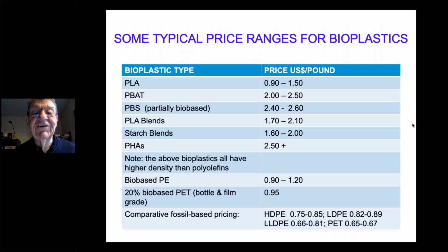So let's talk about markets now. The Achilles heel of all of these bio-based and biodegradable products is price. You can see here, these are ballpark figures, but they give you a good idea that these are very expensive compared to standard petrochemical products, which are down here on the right. The cheapest is just the lowest grade of PLA, and even that's only within spitting distance. And that's for the very lowest property ones, which have very low heat distortion temperatures.